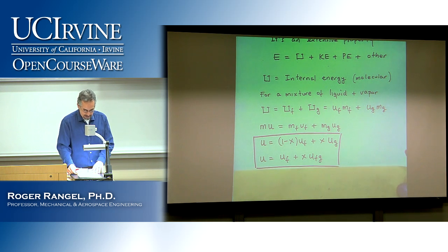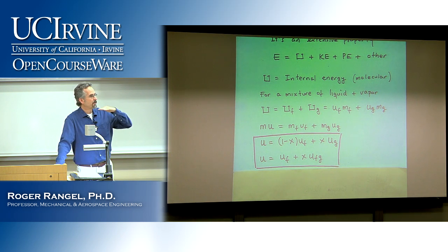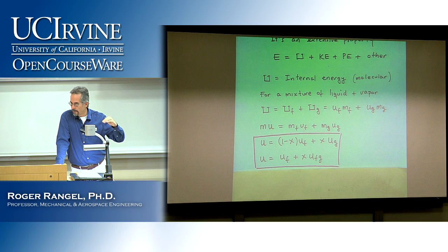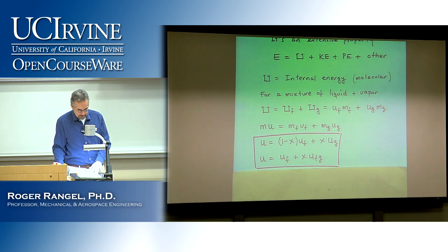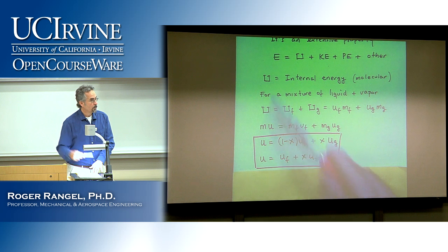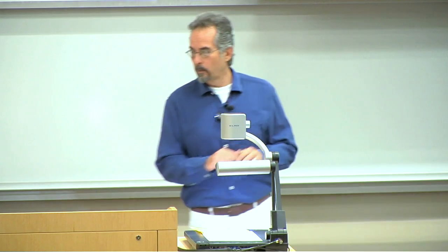Use the quality in the same way we did it for the volume. So any calculation that you could do with specific volume for a liquid-vapor mixture, you can do also for the internal energy of a liquid-vapor mixture. Only thing to keep in mind is that the same care must be taken as to whether you're dealing with capital U, which is extensive, or lowercase u, which is intensive or per unit mass. All right, I will leave it there and see you next week then.